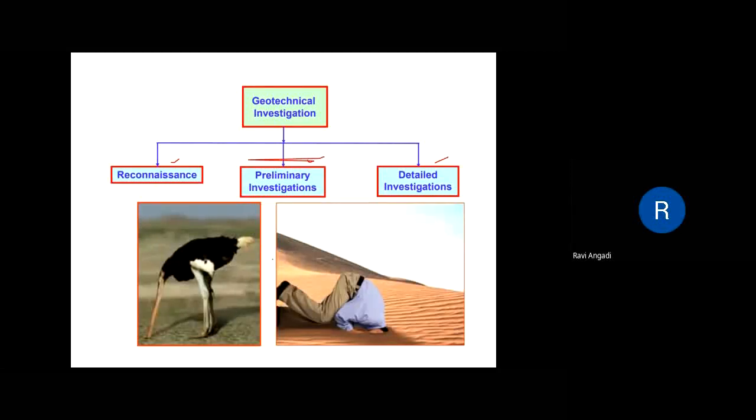Looking at this picture, as I told in the previous class, reconnaissance is just a site visit. It is the very first step of the subsurface exploration program, which includes a site visit as well as the study of maps and other relevant records. That is what we call reconnaissance. The preliminary explorations are generally in the form of borings or test pits.